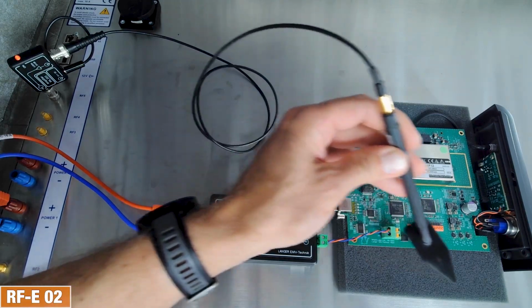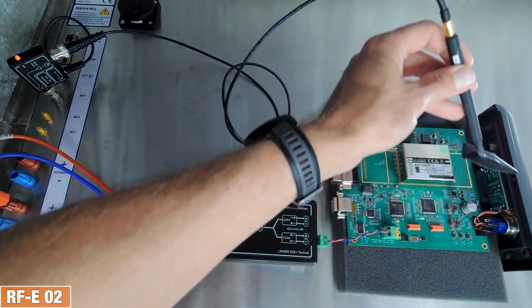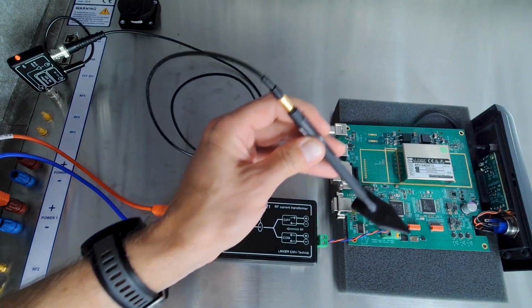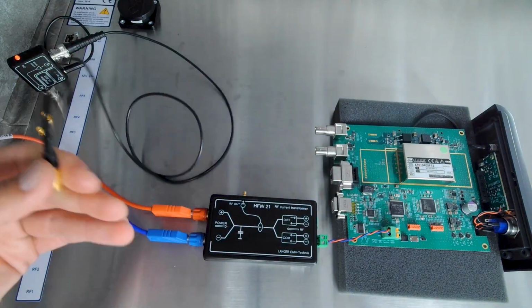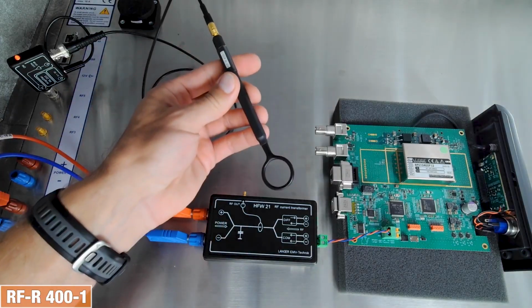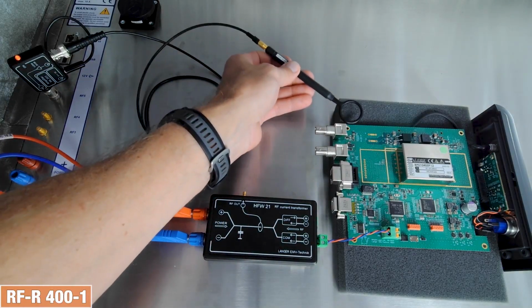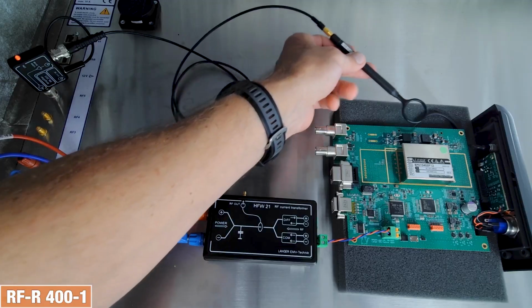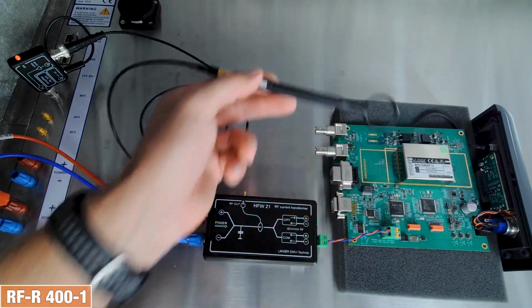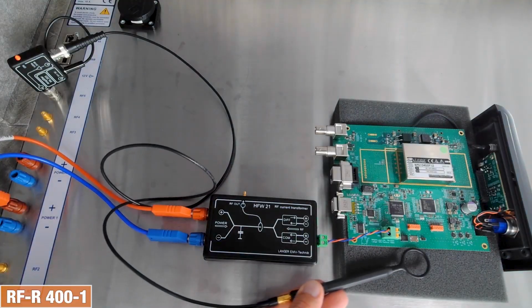Here with these bigger probes, you measure at a bigger distance above the electronic. And the same you can do also with the magnetic field probe. Here I use a bigger magnetic field probe. With this probe you can go along the edge of the board to measure the magnetic fields coupling around the PCB on this side or on this side.